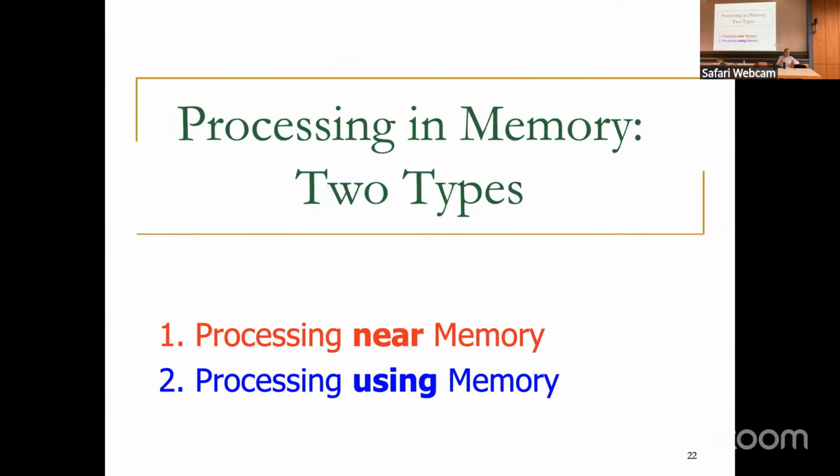So what's the lookup table? Basically, if you want to compute A plus B, for example, you can input a combination of A and B, and that is the address, that's your address essentially. Let's assume that they're both 4 bits each, right? A and B are 4 bits. The combination of them are 8 bits, right? And then you have 2 to the 8 entries.